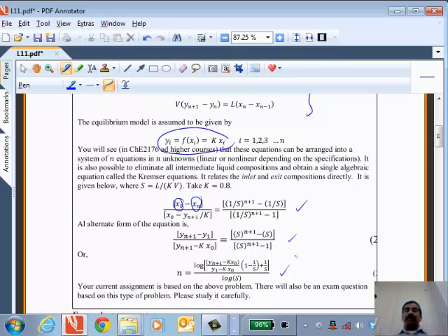Okay? But basically you need to understand, when I give you an equation like this, it has lots of symbols. I explained to you the meaning of each one of these symbols. L is the liquid rate, V is the vapor rate, K is the equilibrium ratio. So S is defined, Y1, Yn plus 1, all these are defined. And when you have so many different symbols in that, if I give you one as an unknown and everything else as a known, you should be able to solve it. Okay? And MATLAB fsolve does that, whether it is linear or nonlinear, it doesn't matter. It will solve the equation as long as you pose it in the correct form. Identify what is the unknown term so that fsolve can solve for that unknown variable.